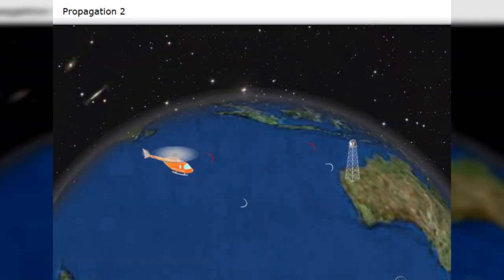Factors affecting propagation. There are many factors that affect the propagation of radio waves and the reception of a signal. Some of these are the ionosphere, sunspots, climate, atmospheric, man-made noise, signal characteristics, and terrain. Skip distance. Skip distance is the distance between the transmitter and the return of the skywave. The skip zone is the distance between the end of the ground wave and the return to Earth of the skywave. Communication in the skip zone is not possible, but the skip zone can be reduced or removed completely by using the appropriate frequency.